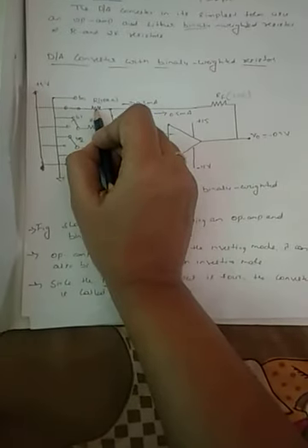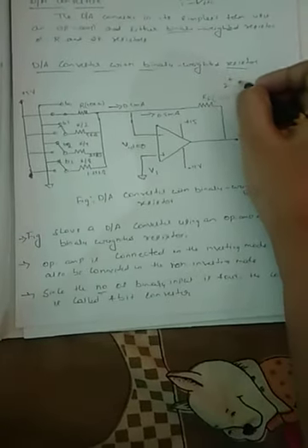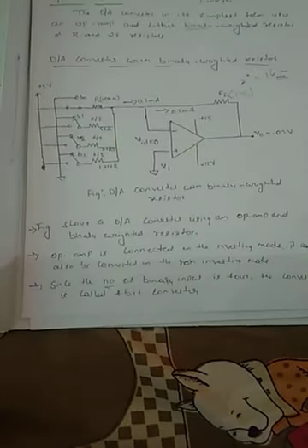Here you can observe that each binary input is connected with a resistor. Each binary switch is connected either to ground or to 5 volts. Since we have 4 inputs, we can have 2 power 4, that is 16 combinations of output.